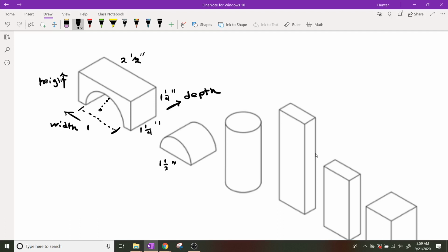But for our purposes, when we're 3D modeling these, we're going to say that the diameter is, I'm going to put D equals 1.5. I can't fit that in. I'm going to try to come up with a way to fit this in without it looking like the width of the object. So, how about this? Diameter 1.5 inches. If you see me write a circle with a line through it, that is the universal notation for a diameter. That does not mean the number 0. You will never see a number 0 written like that in front of an actual number that makes sense.